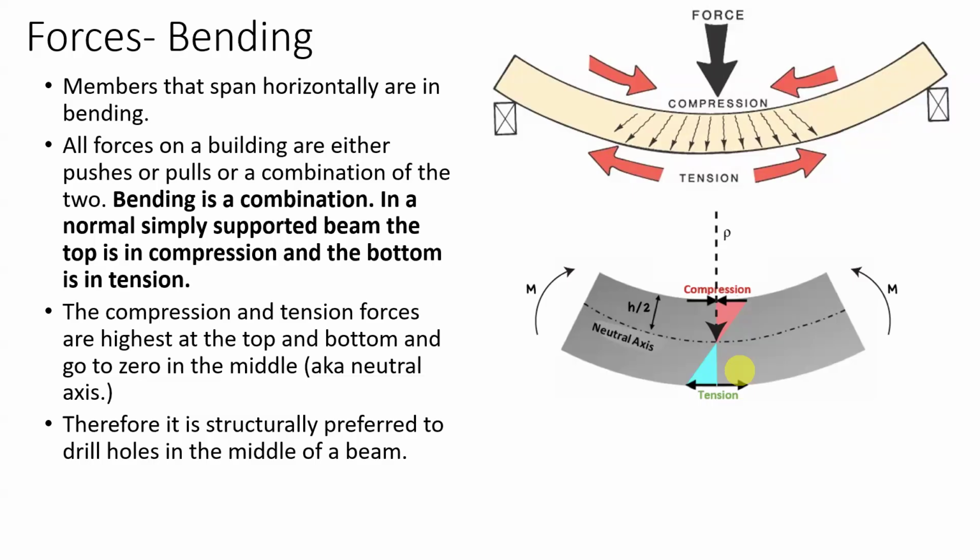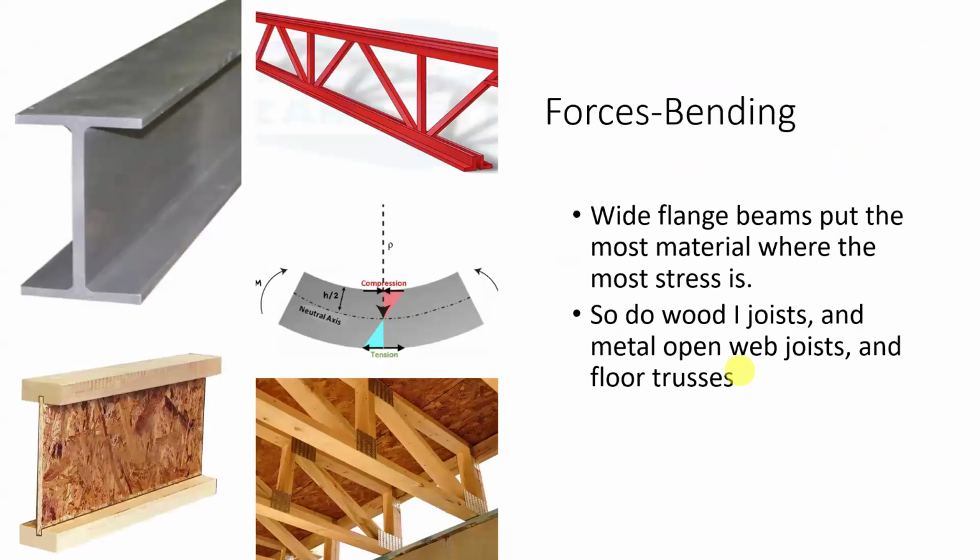And that's why Wimpy Pete can bend this beam just with my fingers this way, and I can't bend it this way, right? Because it's so much stronger in the vertical location. Same way that they don't make diving boards that look like this, right? They were too strong. They wouldn't bend at all if they were straight up and down. They have to be laid flat because then there's no depth there and there's no bending strength there. Okay, so, long talk about why we drill holes in the middle of the beam.